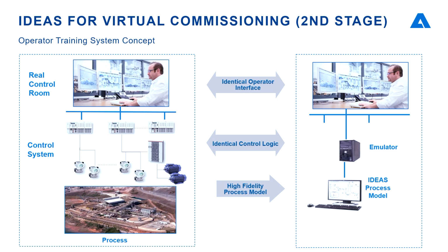So imagine that we are able to connect the fully dynamic models to the control system, the real control program, and when we connect these together, we sit down with your team and the engineering team, and we start commissioning the plant. This is a hot commissioning, virtual hot commissioning. And all those problems, like tank overflow, things not happening, PIDs not working, the control strategy not working, all will come out.